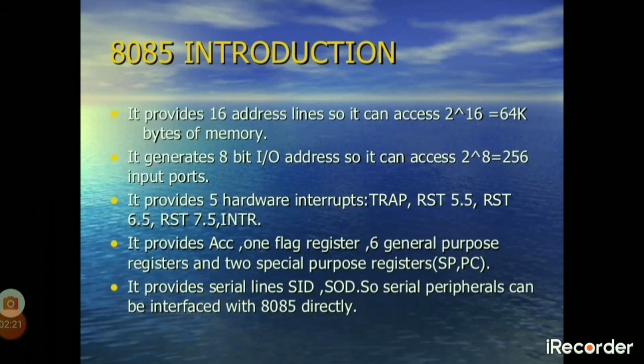It provides 5 hardware interrupts: TRAP, RST 5.5, RST 6.5, RST 7.5, INTR. It provides accumulator, 1 flag register, 6 general purpose registers, and 2 special purpose registers. It provides serial lines SID, SOD, so serial peripherals can be interfaced with 8085 directly.